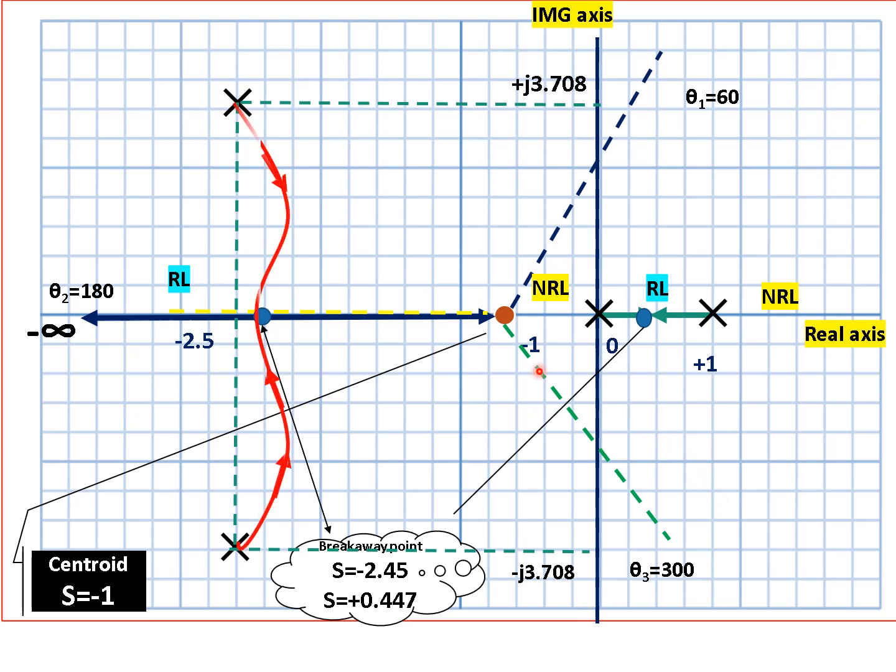Now we try to draw a curve from the breakaway point. As you can observe from this, the root locus line will always move from a pole to infinity or from a pole to a zero. Now this is a very good example of that. The curve drawn is moving, one branch towards the zero and the other towards infinity.